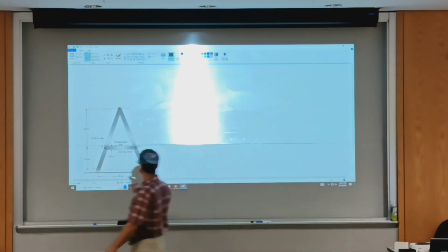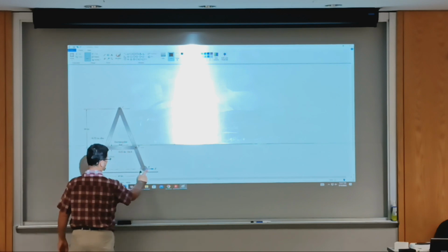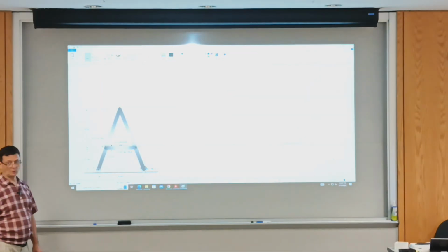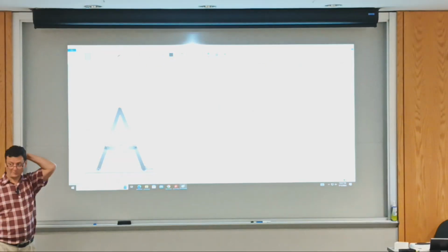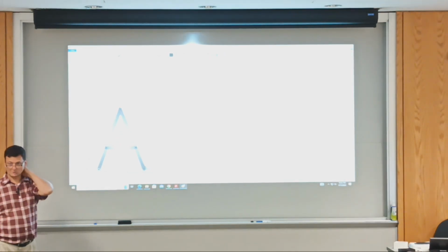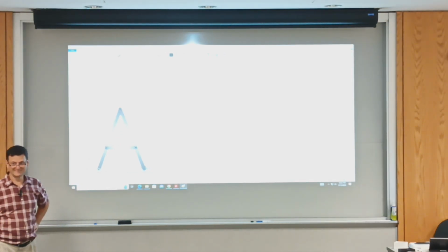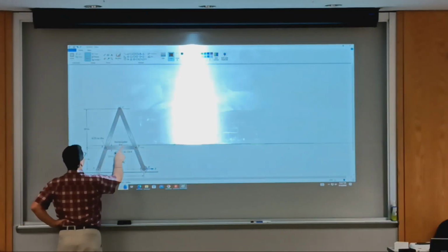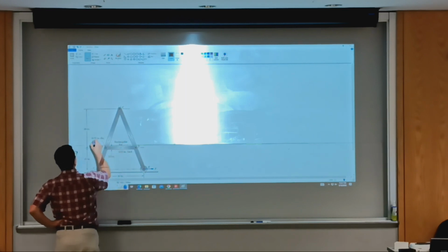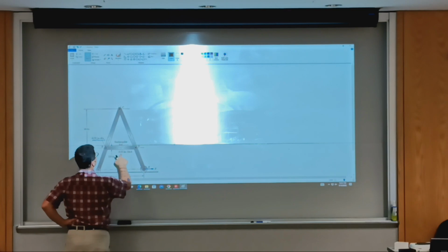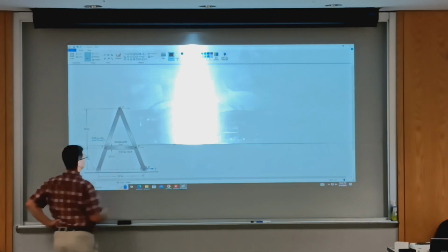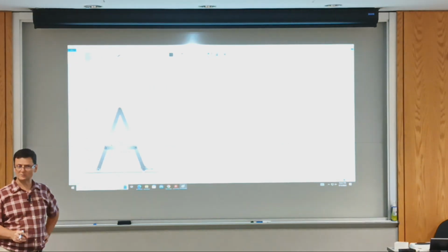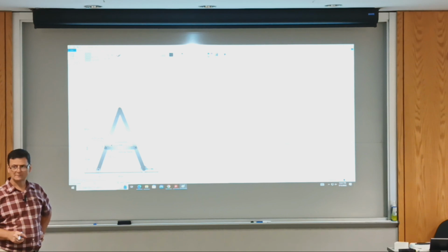So what do we have? We have a pin support, we have a roller with negligible friction, and we have an external force applied at the roller pin. Do you have questions? Let me know if you have questions. It's part of my job description to take questions from students. All right, and this is a round pin, it says rectangular bar. So we need to calculate the shear stress upon the pin, and we need to calculate the stress in the rectangular bar. Does your intuition tell you whether we have compressive or tensile stress in the horizontal bar? How many of you think it's tensile?